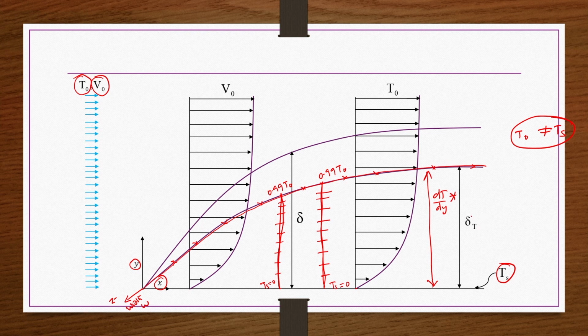right. So, that region we are calling the boundary layer region, whose thickness is delta t, and this delta t is a function of x, that is what we are saying. And then beyond this delta t value in the y direction, when y is greater than delta t, what you have? You have the region where dT by dy is approximately 0.